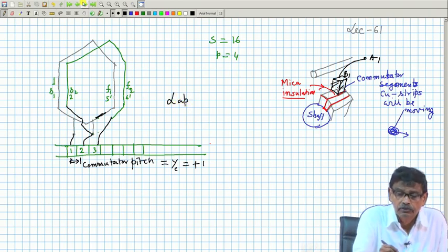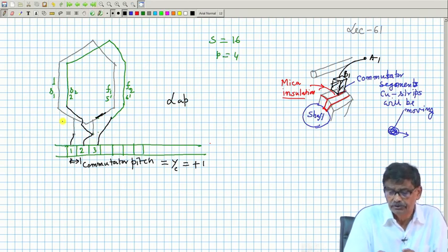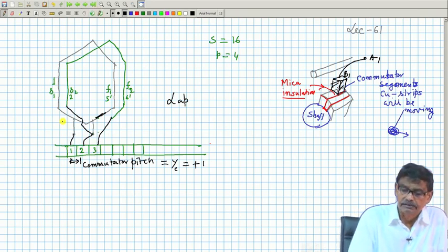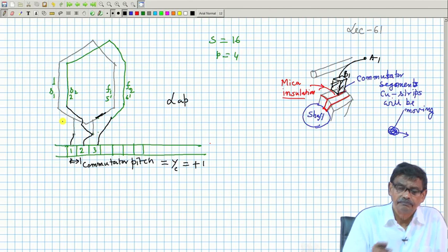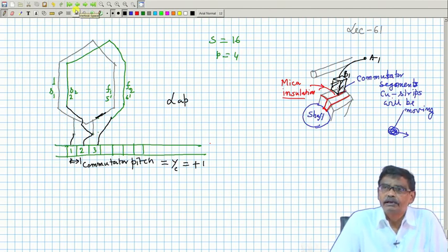Okay. So, after we complete it, then we make the winding table as I have shown, the simplified winding table, and from here I know at which junctions the brushes are to be placed. Everything is known, B1, B2, B3, B4 if it is a 4 pole lap winding, which two are plus, which two are minus. Brushes are stationary, I will connect them and ultimately get the armature terminal. Okay.